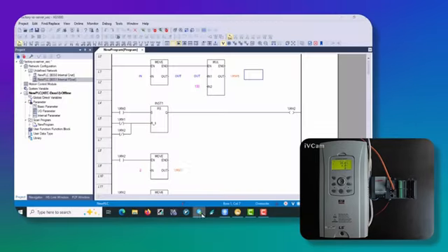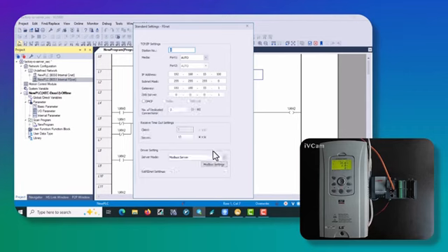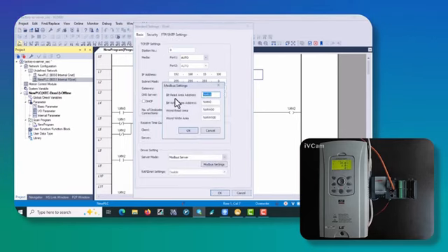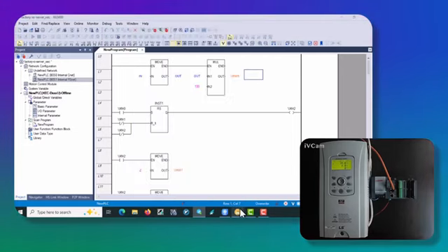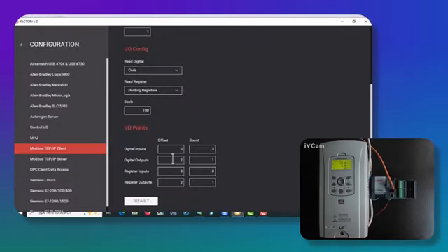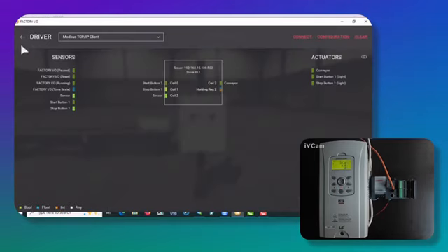Why? If you paid attention, in my PLC here, in the Modbus settings, I set the address for the bit read area to MX2, meaning I started from the second address. So in the factory I/O software, the digital out should also have an offset of 2, meaning my address should start from the second address. Well, I don't need the input register, but my output register also needs to start from the second address, and I only need 1. Alright, but these were the settings we made in the factory I/O section.